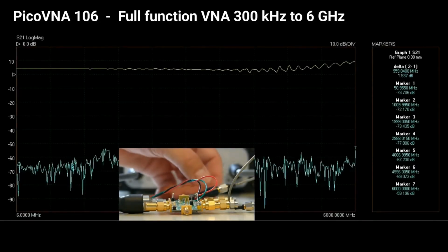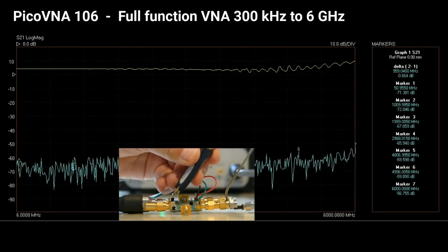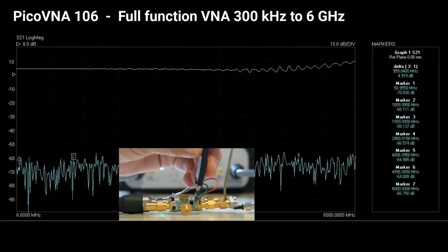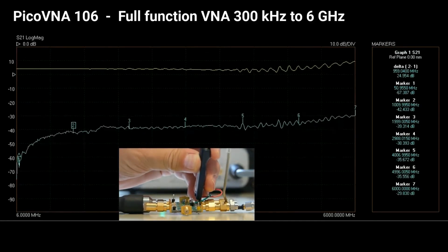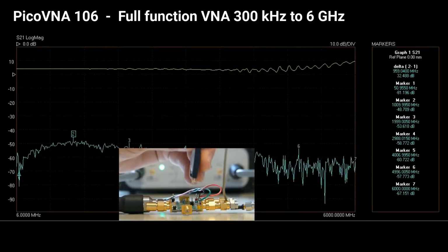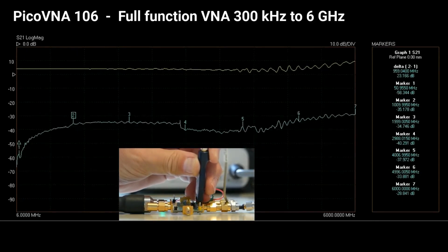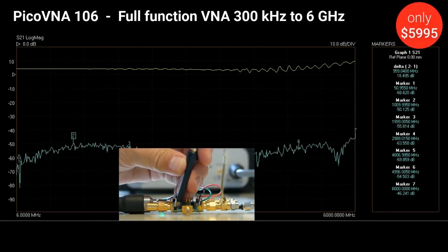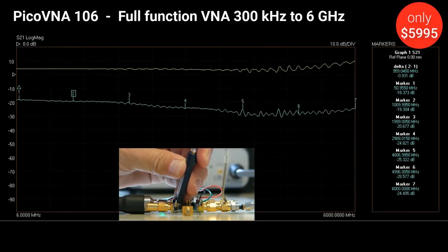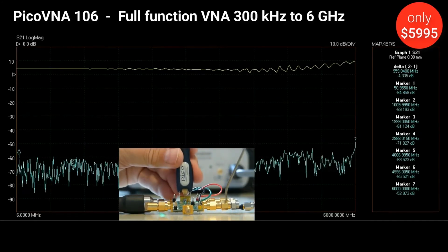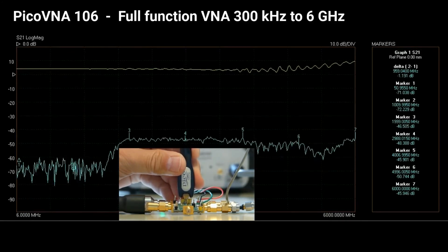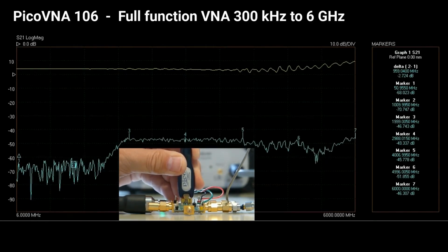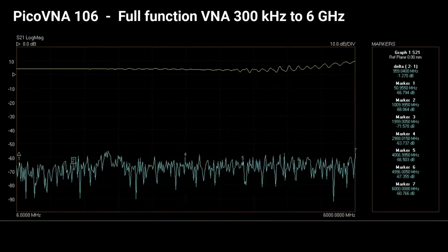Finally, let's pair the PicoVNA 106 with an AC coupled Pico Connect passive probe. Here we're going to make the most of the VNA's speed to browse S21 responses around signal, control, bias and supply nodes of up to 50 volt DC bias around this amplifier. We find there is a -20 dB non-flat swing on the unused input and a -45 dB plateau on a decoupled bias supply, and both were very quickly gathered.